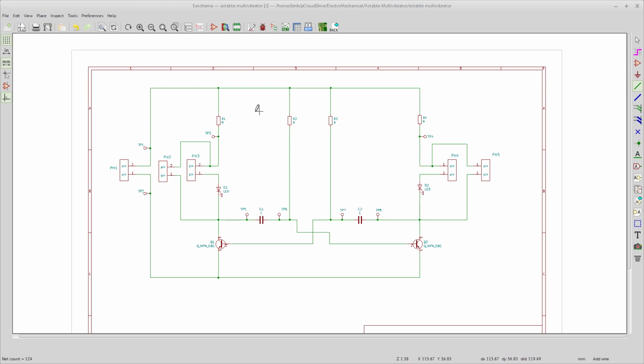Now the annotation, it's got the auto annotate, and it did it mostly fine. It put 1 and 2 over here, and 1 to R1, R2, R3, and R4 right there, and that was good. But the test points, I wanted them a little bit differently, and here's more of the point to this: you can run the auto annotation, and maybe you probably should, but a lot of times things kind of go together. For example, these test points down here around the capacitors, my thought primarily is to check the charge across the cap, and so I probably want them sequential, and the same over here.